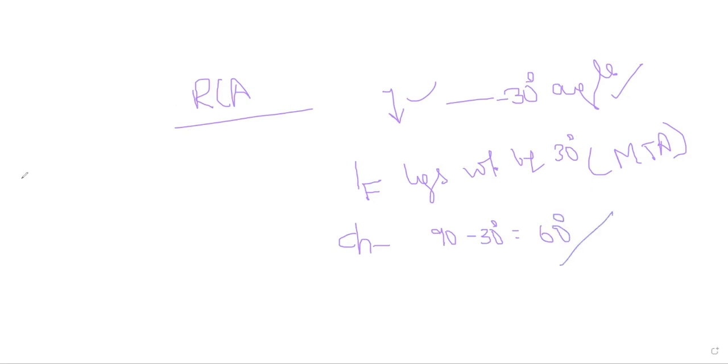In our earlier diagram, I showed you that V reference is the voltage that is applied to the relay, and this is the current that is applied to it, and we have one more line. This is the maximum torque line, right? This is the phase angle between them, so this is the direction. And I said there is some difference of 90 degrees, theta plus 90, right?